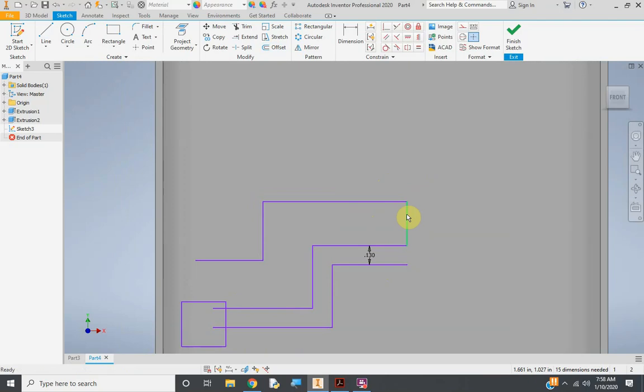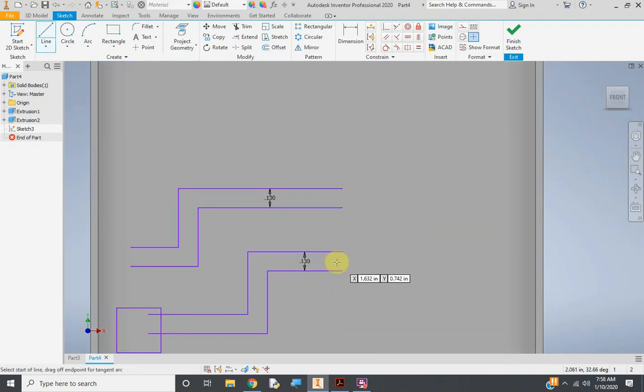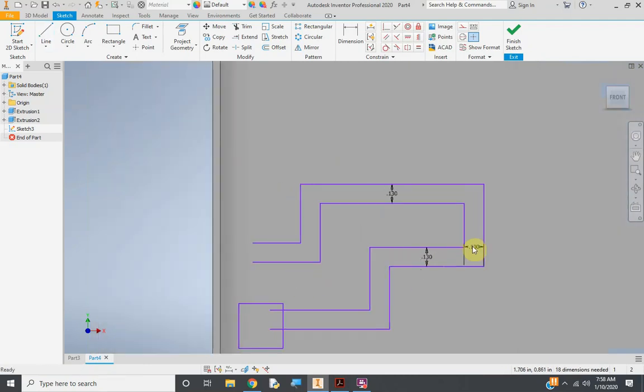If that happens, just don't connect it, delete one part of it, hit O, 0.13. And then what you can really do is, if you want to connect these, draw a line that's 0.13 over, 0.13, enter. And then you can just connect them like that, okay? That works just fine, all right?